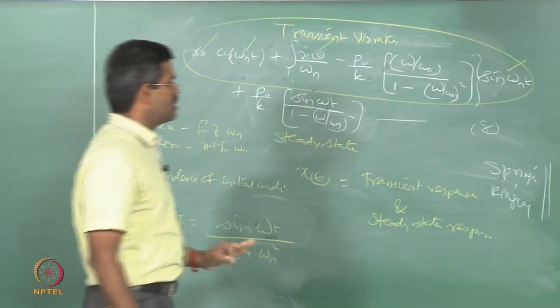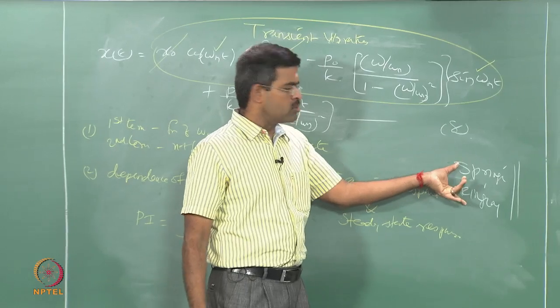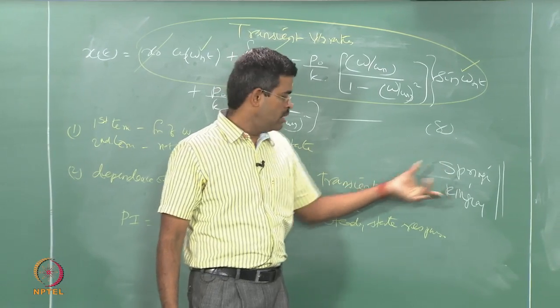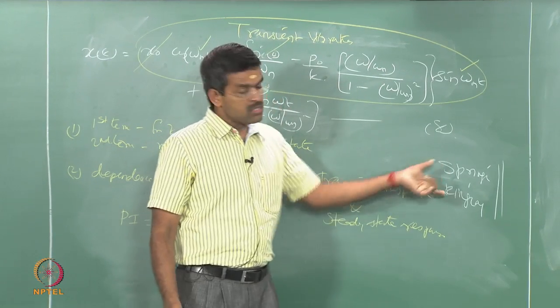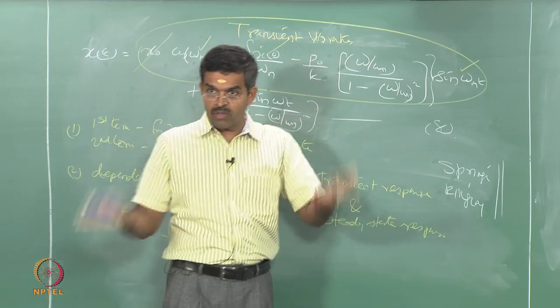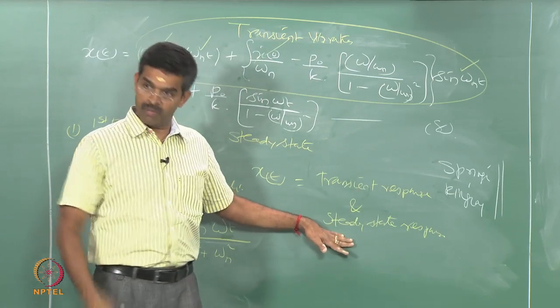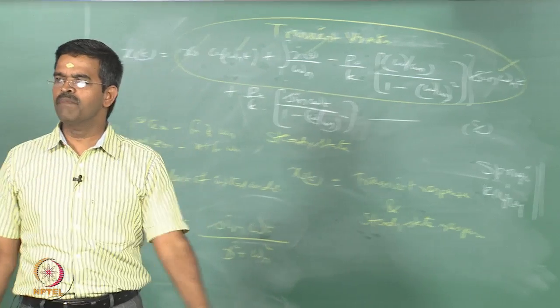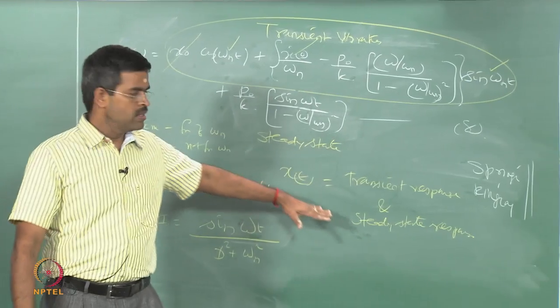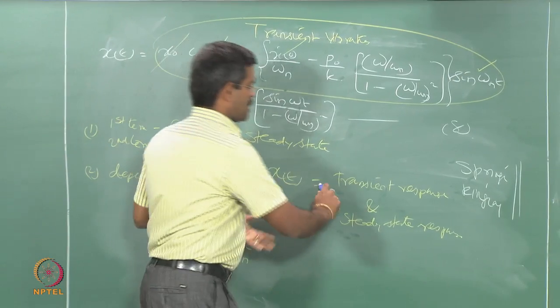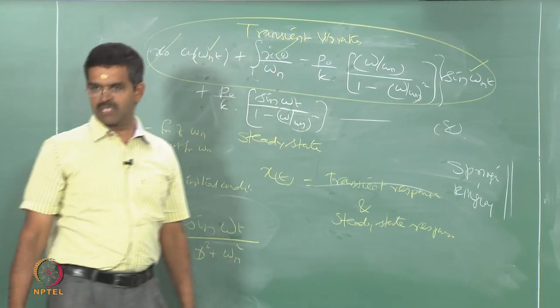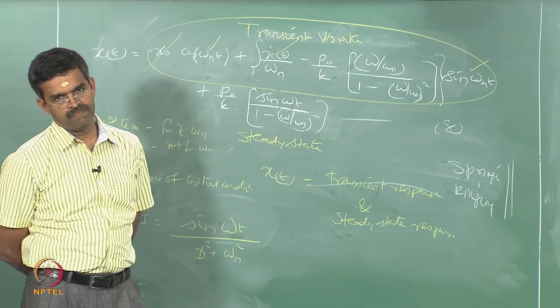Here it is important because of springing and ringing, we will talk about this in module 2. I will tell you how this becomes important, which can cause instability to a platform even though steady state response may not be important. So, very important, we cannot ignore this. Generally people neglect this, they say it is not important and so on, but that is not the case in offshore structures.